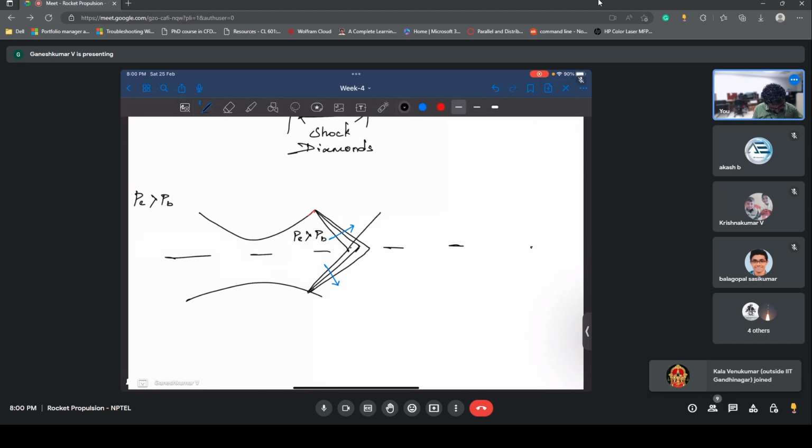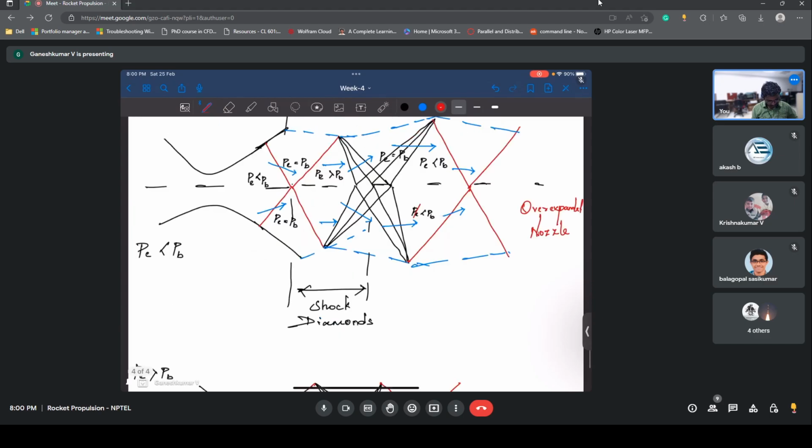The reason to form a shock is to reach the downstream condition in a supersonic flow, simply if you want to state it. If there is no supersonic flow, you always know what the downstream condition is, because you can adjust it throughout. So that is the reason you cannot have a shock when the Mach number is less than 1 at the throat. Is that clear?